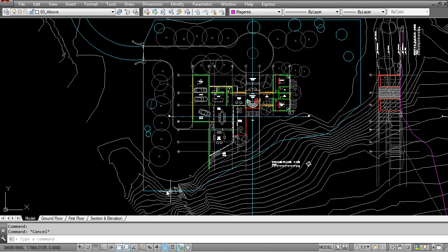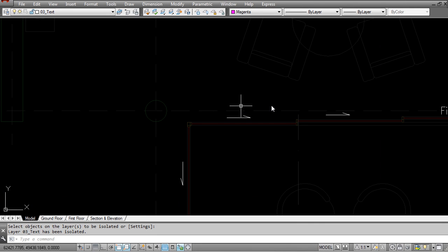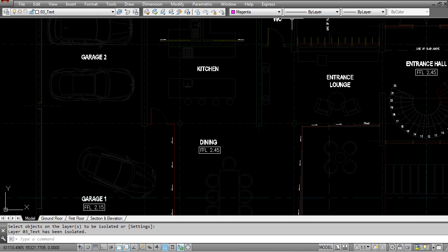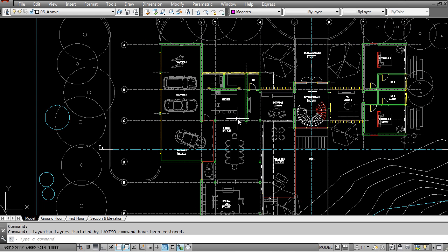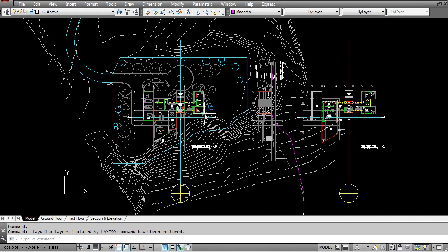So get rid of as many labels as you can. You can use the extraction method that I showed you in the last lesson. For example, here I'm going to click on the text, extract it, and then just go and delete as much text as you can. You don't need all these arrows, although you can keep them, or you can even refer back to the plans as you're busy modeling, which is something that I like to do. So the rule here is just extract as much as you can, leave as little as possible, and whatever you do leave, make sure that it's simple geometry that can be easily read and doesn't slow down your viewport manipulation in 3D. So that is it for this lesson.